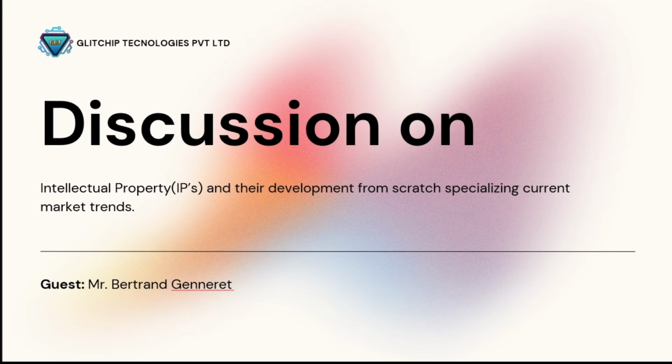Then once you have validated your RTL code, you go to synthesis. In this step, you will convert your RTL code into a gate-level netlist. And during synthesis, you will optimize your design for area, speed, and power. All those optimizations will be based on a specific target technology library for hard IP.